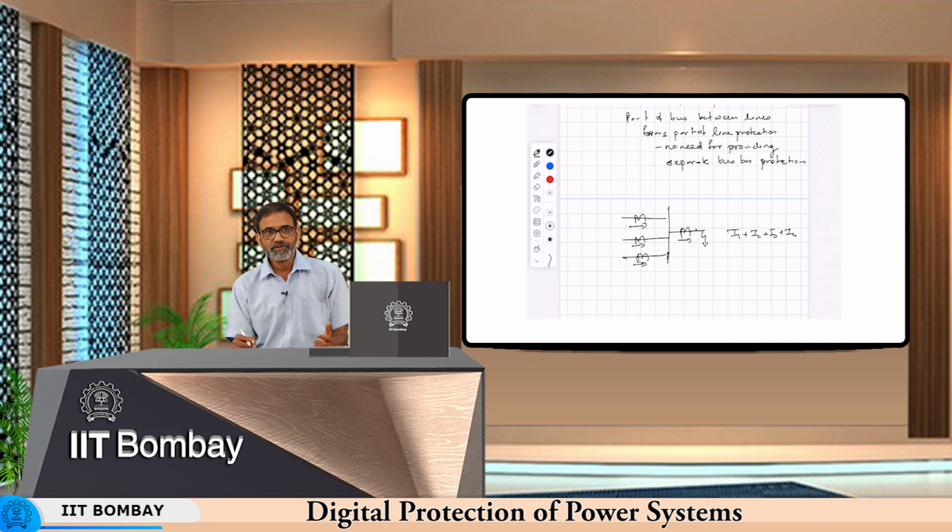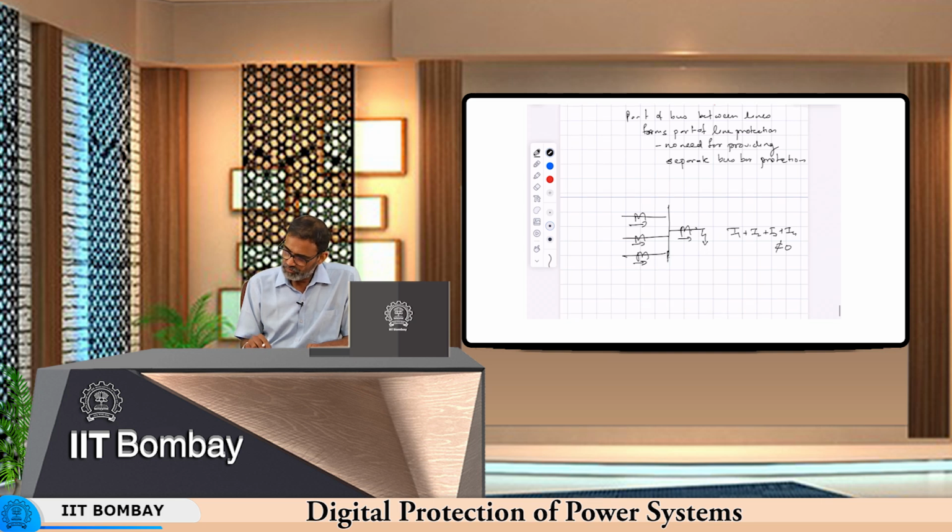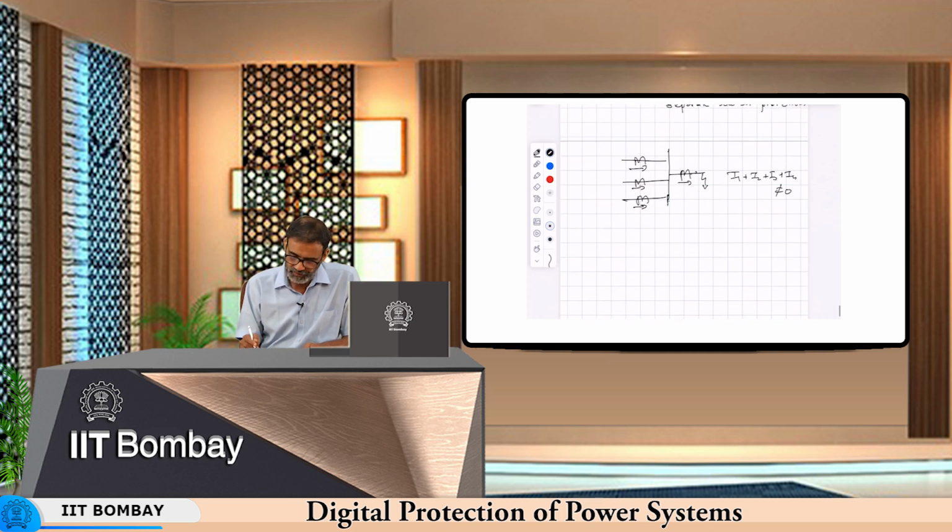The relationship between the primary and the secondary is lost. It starts behaving like an air cored reactor, and on a circuit level all the current will flow through the magnetizing path, and then it is not reproduced faithfully, and the relay will not see the current. So, this will not be equal to 0, and even when there is no fault, a fault will be seen. Okay. So, there are ways of overcoming this.